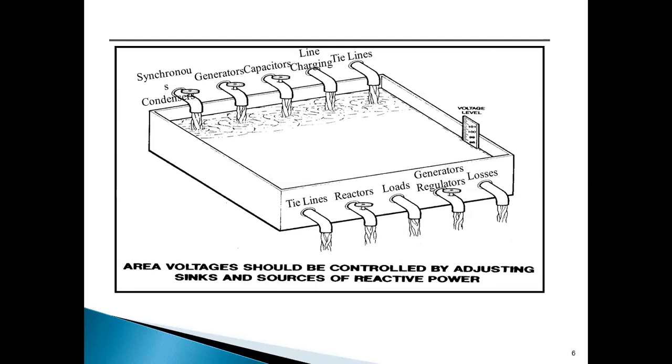And for example, capacitors in the transmission line, we have got a series capacitor. Capacitor, we are generally aware, has the capability to generate reactive power. It will generate only reactive power, and an inductor will absorb reactive power. These two points are to be remembered, and you are all familiar with them. In case of a transformer, as it is inductive, it will absorb reactive power. And underground cables, the major dominant effect is capacitive. Therefore, based on the net capacitive effect or inductive effect, we can classify any power system component into either a generating or an absorbing device.